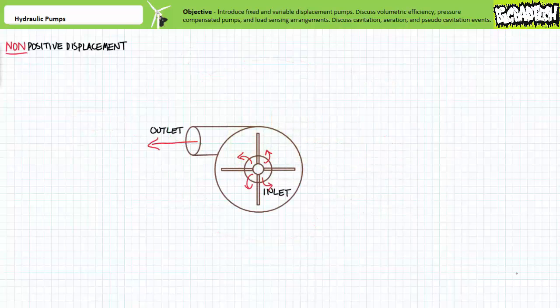To compare and contrast the features of positive displacement pumps, consider the alternative, a non-positive displacement pump. Non-positive displacement pumps are those characterized by no clear and definite separation between inlet and outlet stages and are ordinarily only used for low-pressure fluid transfer applications. A non-positive displacement pump, like an impeller pump, has large clearances between moving components and is not ordinarily self-priming, in that inlet fluid passively spills into the pumping chamber.